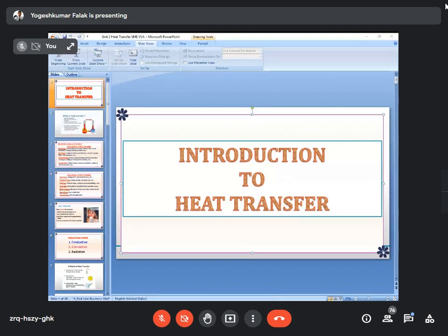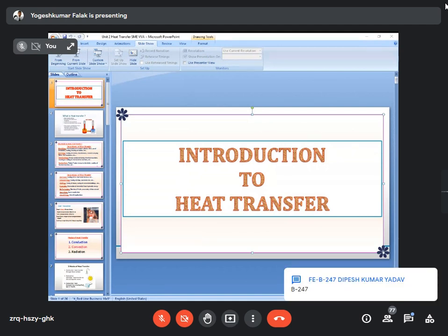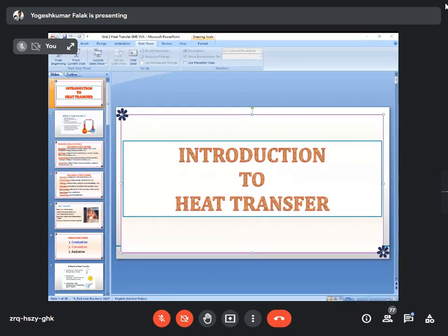So when heat moves from the inner surface, that is the combustion, to the outer surface of the cylinder, if you touch it, you may feel it is a hot surface. Am I right? Yes, sir. So the heat is distributed by means of conduction. So it needs some cooling, right? To increase the cooling rate,